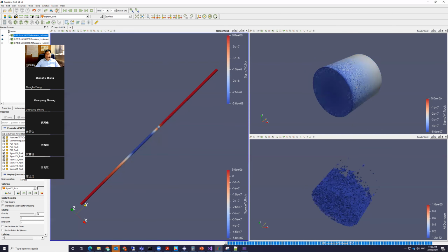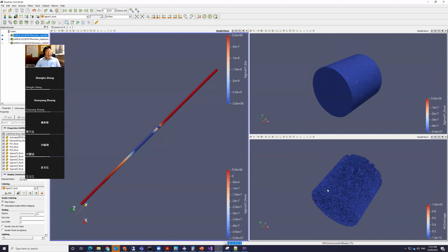If you look at the damage value D, it is quite small, which corresponds to 0. The sample is highly stressed everywhere, so macro damage is happening everywhere. But although there is macro damage, it is not the formation of a macroscopic crack. The value here is almost equal to 0, 1.2 times 10 to the minus 12. Essentially it is almost zero.